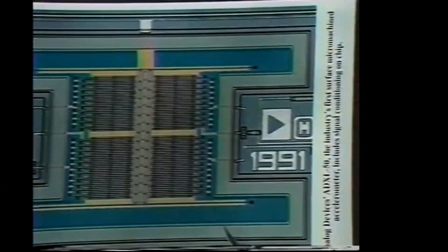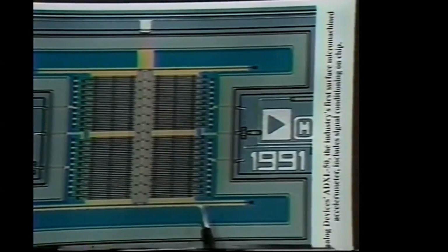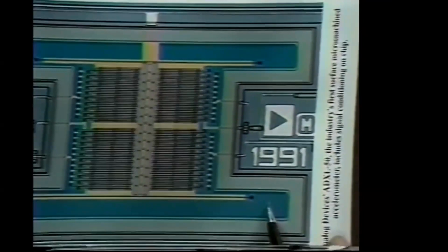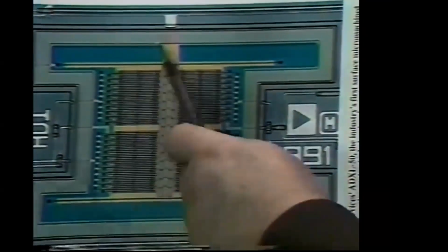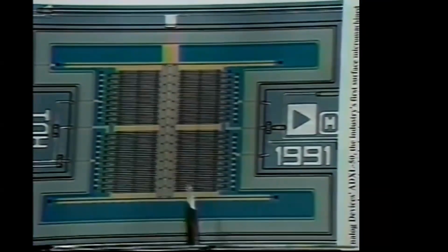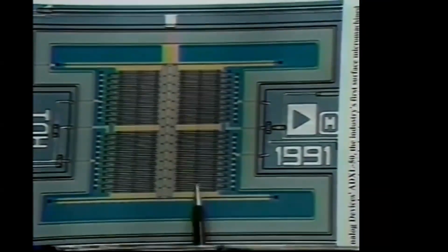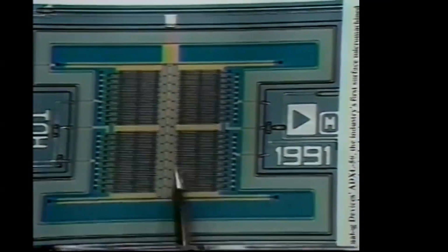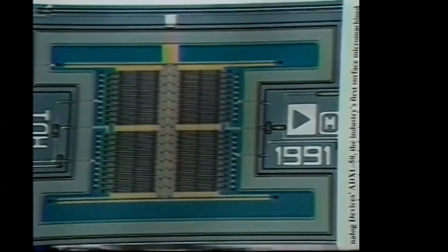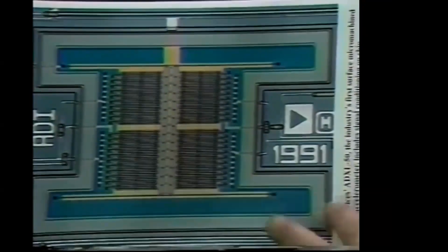These thin films are dielectrics on the order of a half wavelength of light, and they show the tether. The sensor in actuality is 42 differential capacitance cells. Half of the proof mass is in the fingers that stick out and half the proof mass in the center member. And again, this resides about 1.5 microns above the surface of the silicon.